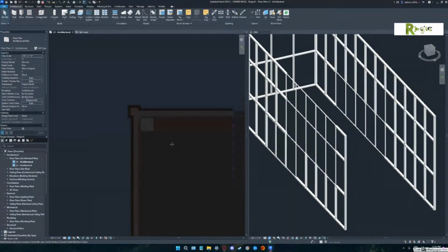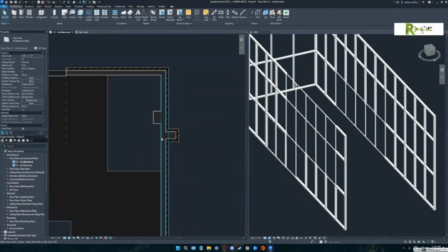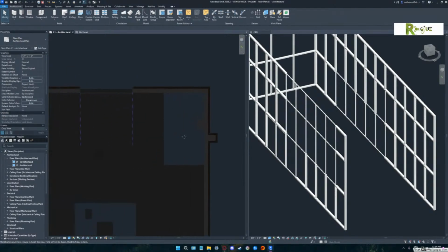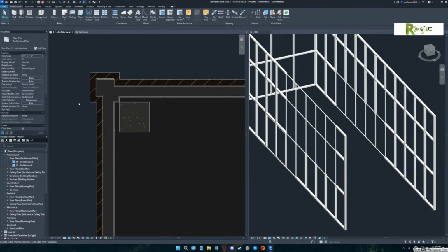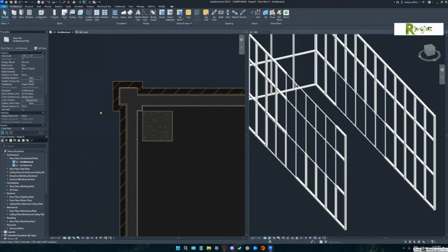Right. And you see, one of the things that we end up doing with Revit is that nudge, the arrow, the command. We also end up dragging things. So like that column, if you zoom up to where you had the two columns in the corner that I was breaking up, zoom up in there. You see the bottom column, you see how it thinks it's concrete, it has the little speckles on it. Yeah. If you just click on that and drag it and bump it into a wall, watch what it does.